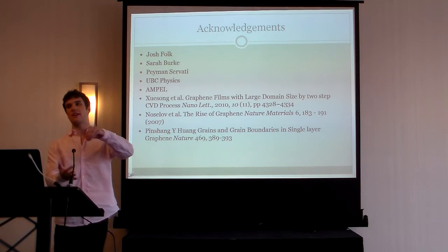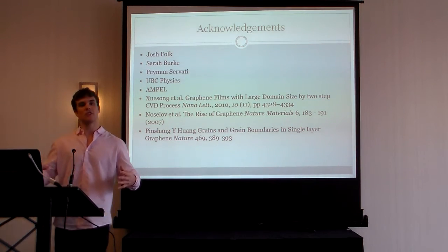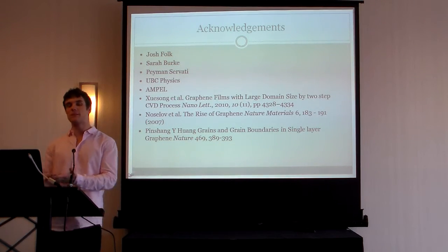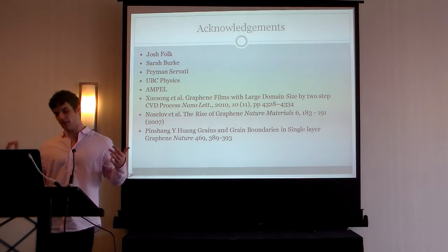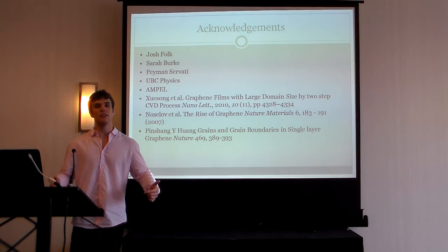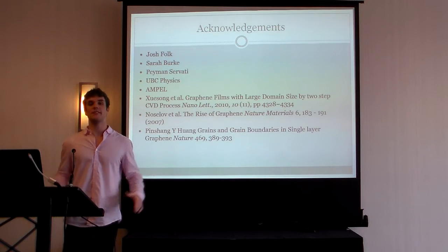That's the main difference, because you're going to get multiple seed locations throughout the copper, and then they all grow to meet each other. The only problem is, depending on your application, at these grain boundaries you get a lot of heptagon-pentagon defects, so they're highly resistive, and you can't measure ballistic transport, for example, across a grain boundary. But yeah, it's unlimited size.